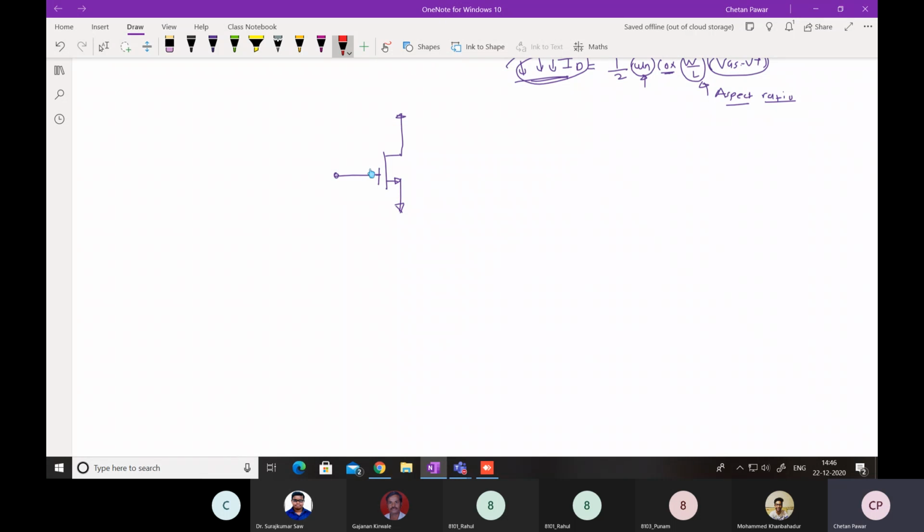Go to the ADE and tools, result browser. No, in ADE, sir. Tools, result browser. Just click on that. Now you can click on that plus sign, the upper one. Yeah. DC output info. Yes. DC output info. This one after DC output.